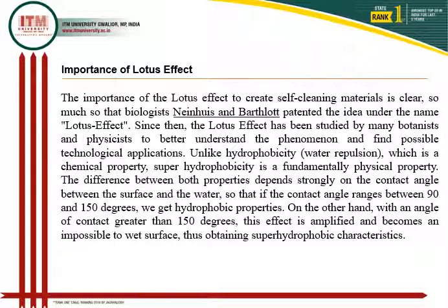If the contact angle between the surface and the water droplet is between 90 and 150 degrees, then we observe hydrophobic properties. But when the angle of contact exceeds 150 degrees, this effect is amplified and it becomes impossible to wet the surface, and this is called superhydrophobic characteristics.